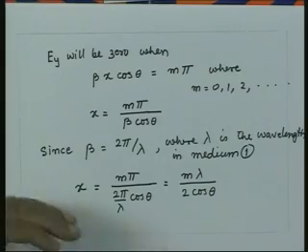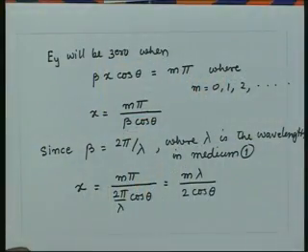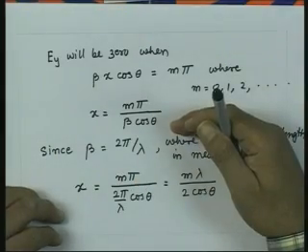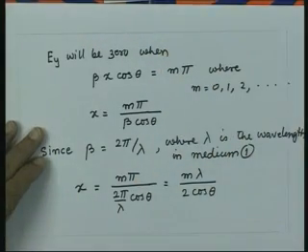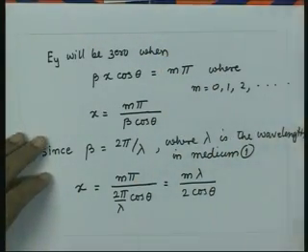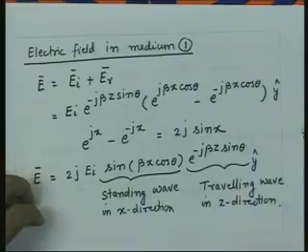So, what we find is that when the wave is reflected from a conducting boundary, we have created planes parallel to the conducting boundary where the electric field will be 0, and the whole wave is going to travel along the direction which is along the interface.